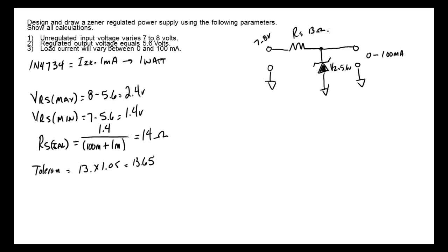So RS we'll use 13 ohm. And then we're going to calculate the wattage. PRS would be equal to your maximum voltage, right? 2.4 squared over 13.